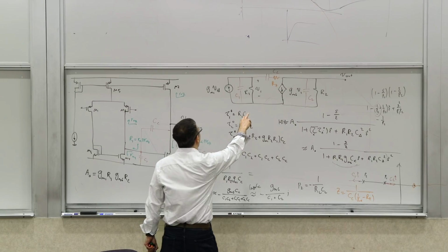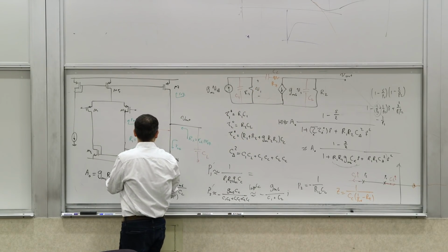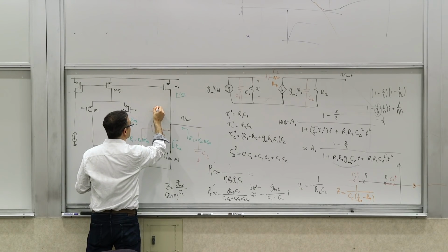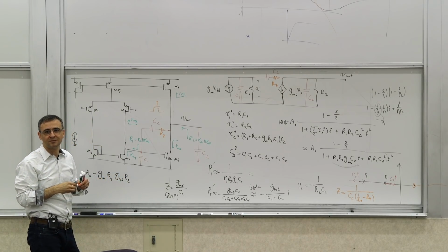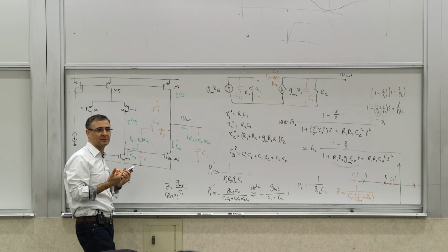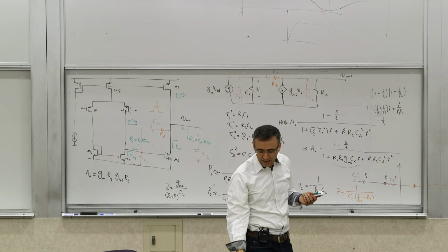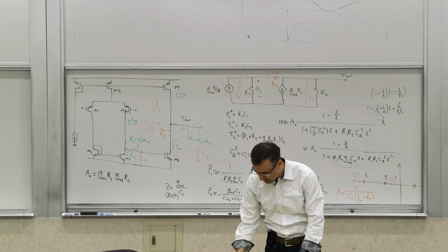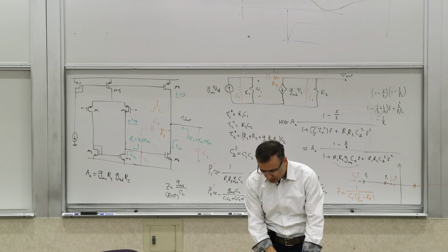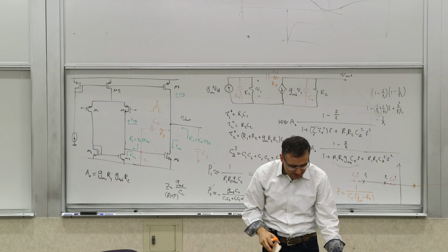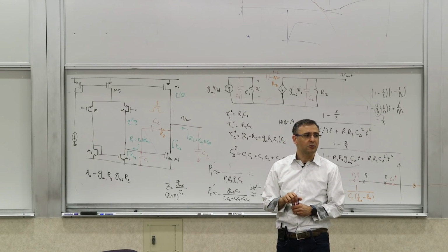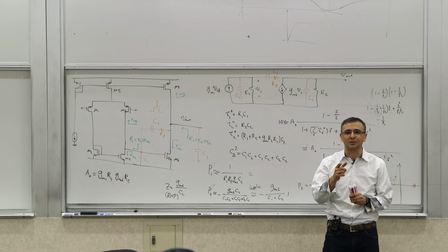So you will see this also very commonly, that when this compensation is done, there is a resistor in series. Sometimes this resistor is implemented as a MOSFET that's biased in the triode region, not in pinch off, in triode, as a resistor, if you want to make it tiny. A lot of times it's just done as a resistor. And that compensation helps you a great deal. Okay, so that's for frequency stability and compensation. These are just some examples of how that can be achieved. There are lots of different variations of this and different ways of doing this. Any questions?